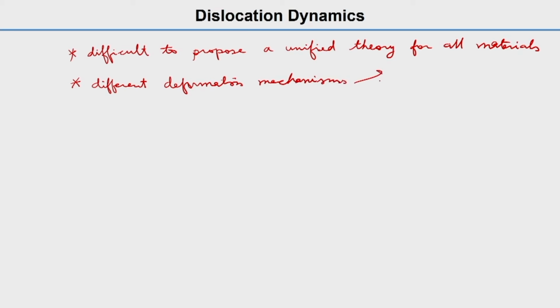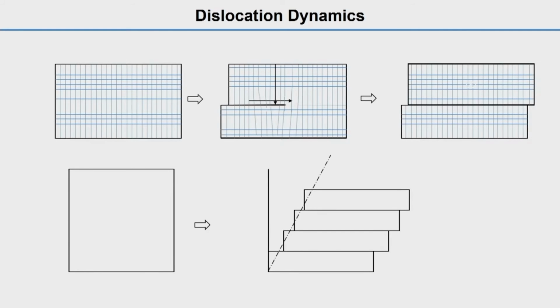As we know, we have dislocation slip, twinning, and phase transformations, mostly we discussed martensitic transformation. So in this section we will only talk about slip, that is dislocation slip, not the other two. Here we will talk about edge dislocations. Here we have an edge dislocation. I hope this figure is clear to you. So this is an extra half plane.